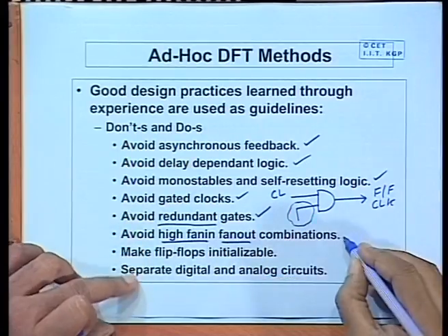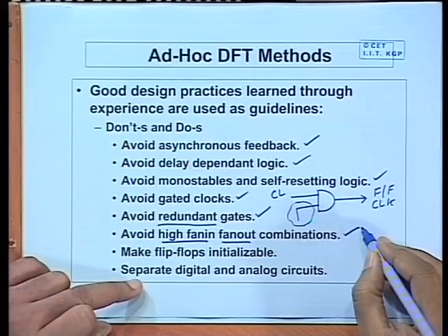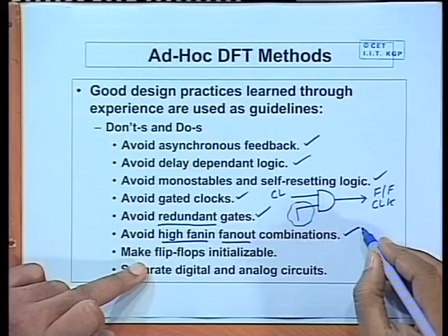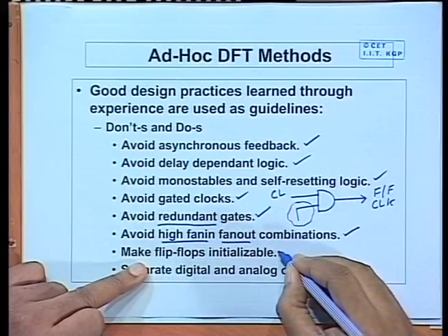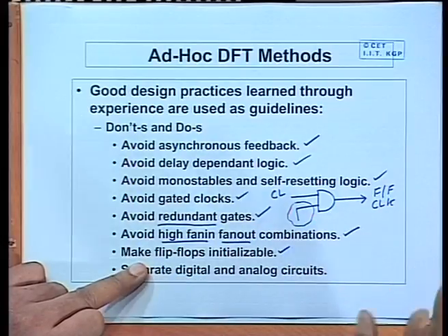So, if there is some redundancy in the circuit, your fault coverage can go down significantly. So, you try to reduce redundancy. Do not use high fan in or high fan out, because these are not good in terms of circuit performance and also reliability. So, all the flip flops should be initializable externally with relatively less effort.